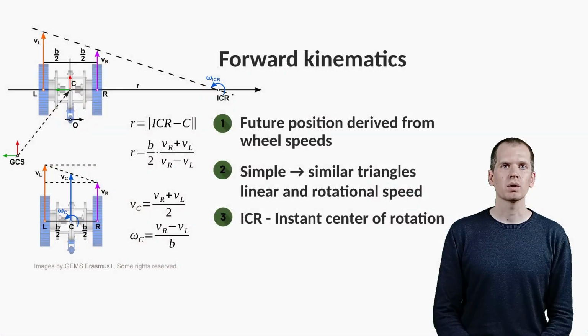With a constructed mobile robot with a differential drive, we can discuss its kinematics. That means we want to describe its movement in a more formal way with equations. There are two possible questions about the robot's movement. First, where will the robot move with certain rotation speeds for its two wheels? Second, what could the rotation speeds of the two wheels be to get to a certain position? For the first question, we need forward kinematics, and for the second, inverse kinematics.